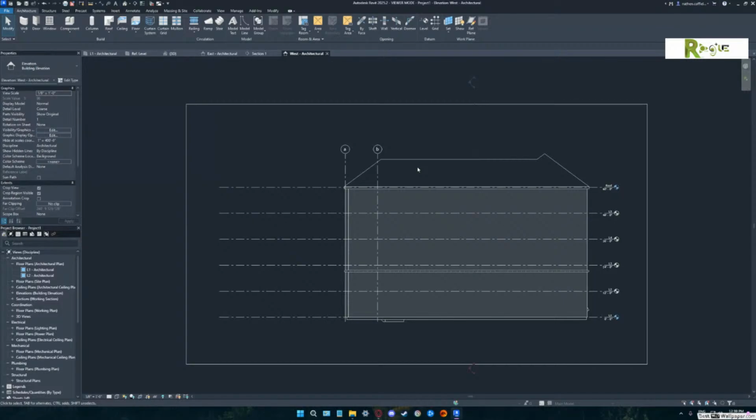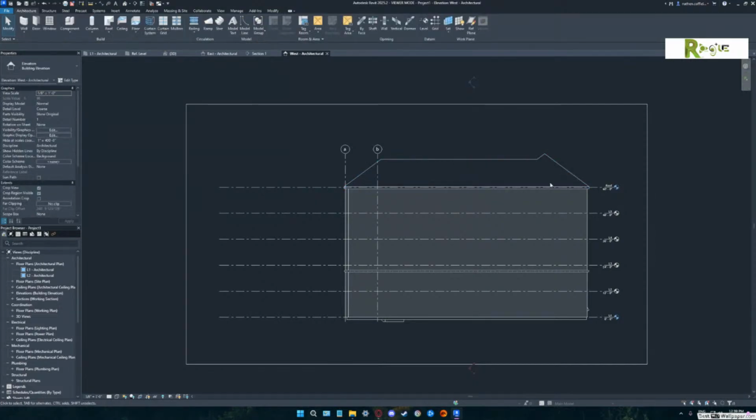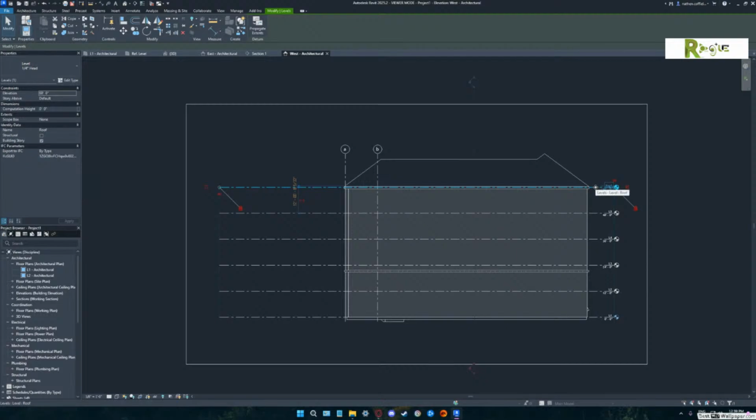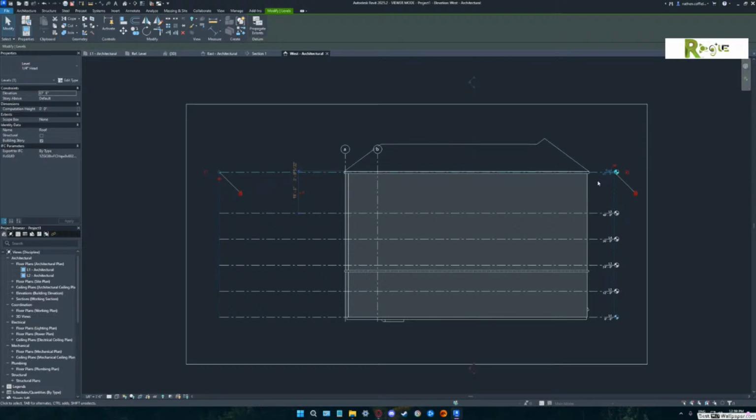Well, here's a neat thing that happens. Take your roof and nudge it up maybe like we were going to add another floor. I'm sorry, the roof level line. Don't ever pick the target. There you go. Pick that. Now just hit your shift about 5 times or your up arrow a bunch of times. Do you see how the column lines aren't moving? Keep going. All right, stop. See how those column lines didn't move up.